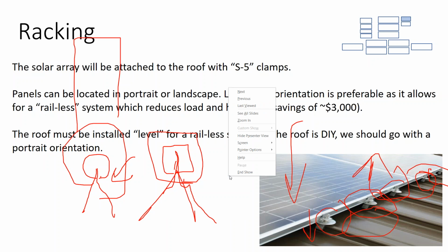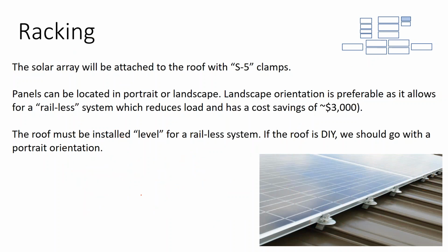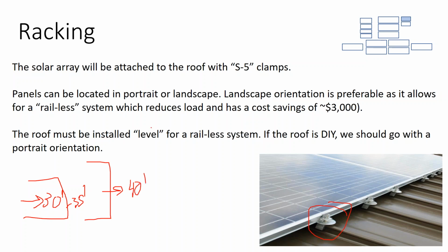We also ran into another problem with the racking system in that this standing seam bracket is designed to accommodate a wide variety of modules. Now, module frames are generally 30 to 35 millimeters. And if you get a more robust module frame with a little bit better wind rating, it might be 40 millimeters. But there are some modules that go all the way up to 60 millimeters.